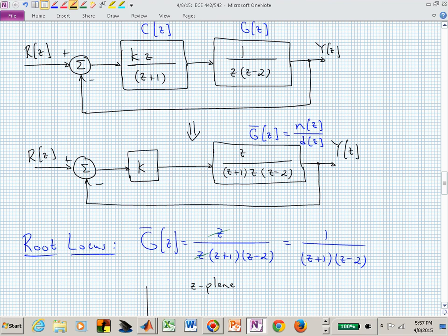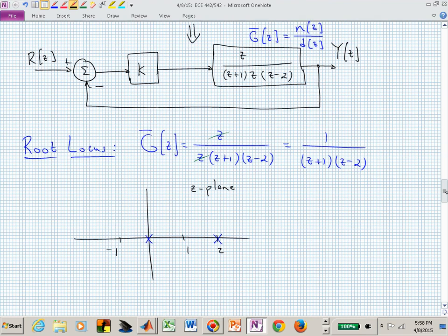It's not unstable, is it? That pole and 0 cancellation is inside the unit circle. That's okay. I can't make those cancellations with anything outside. Or what do I have? I have a potentially internally unstable system. You may not see it from the reference input to the output. It'll be oblivious to that cancellation, but another transfer function is going to not be acceptable.